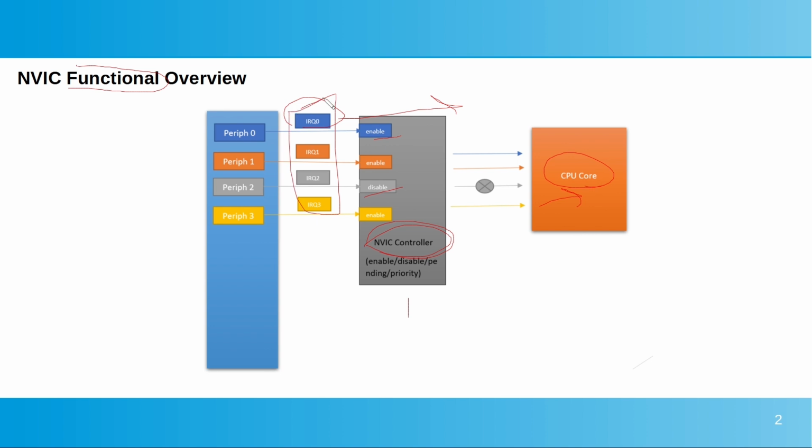It allows as well the tracking of the state of the different interrupt lines, whether they are in active state, meaning the CPU core has already received the interrupt line event and has jumped to the corresponding ISR handler, or in pending state, meaning the CPU core has already received the interrupt line event but didn't jump yet to the corresponding ISR handler, or not active state.